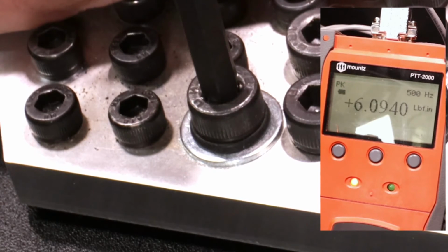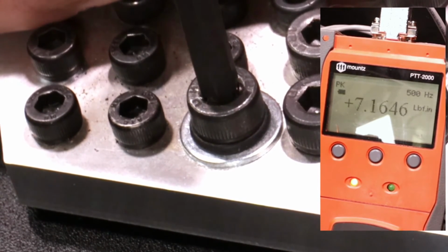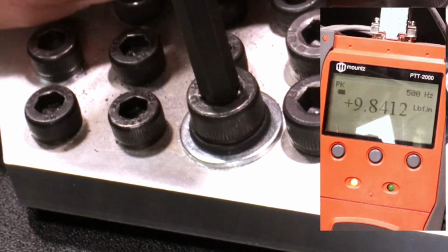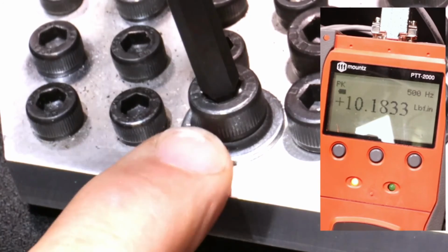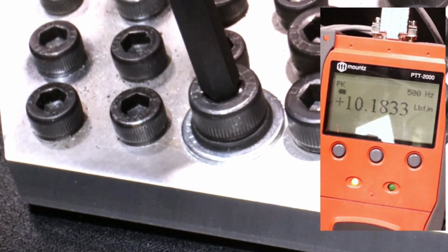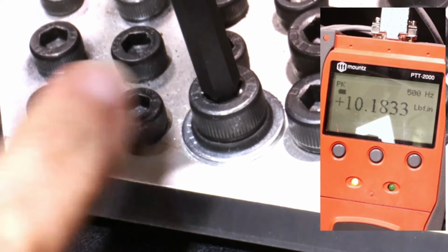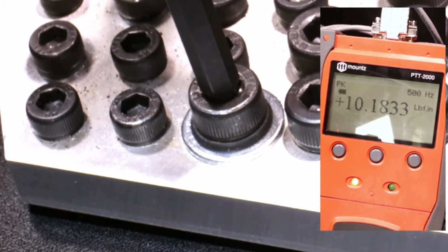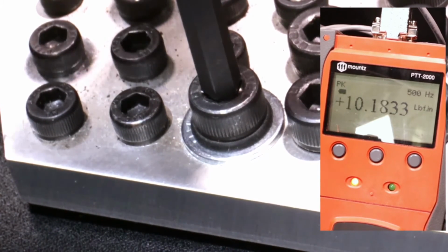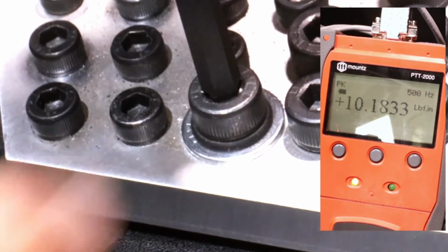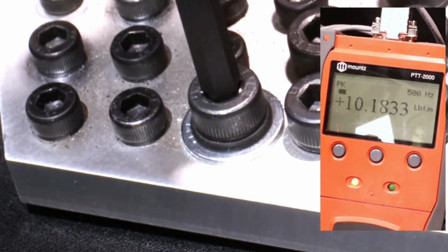And so as we're applying load, we get a few degrees of rotation, and you can see that because of the joint relaxation that we are seeing here, we torqued it to about 17 or so inch-pounds. But when I do up my first movement test, you can see we're at just over 10 inch-pounds. So there's quite a bit of relaxation that's happening from when the tool shuts off because of the softer type of joint that we see here. And this is the result from that particular first movement, because we are turning the fastener in the tightening direction.